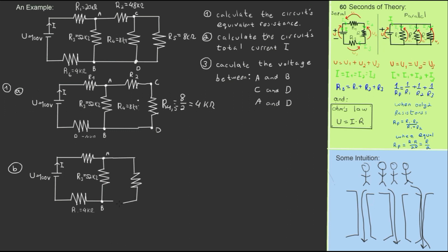That's our new resistor, R245. And what would be its value? It's the serial connection of two previous resistors. One equals 4 and the other equals 48. We use the rule for connecting resistances in serial, and R245 would equal 4 plus 48. That would give us 50. Sorry about that. That would give us 52 kilo.